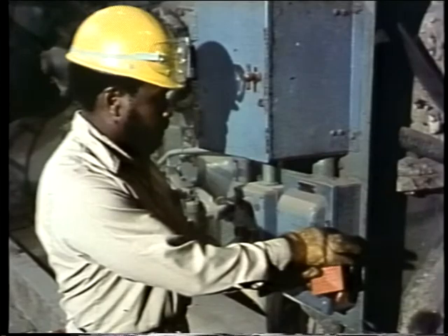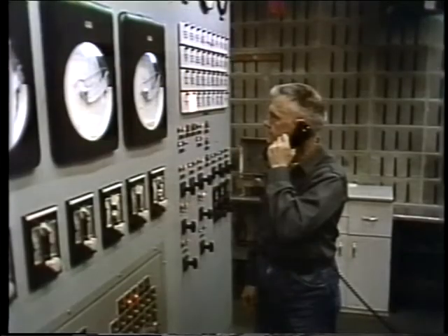Hold tags on the associated systems can then be removed, and operating personnel can run the soot blower through a final test in place. But remember, final testing must wait until the boiler is fired so the soot blower can be observed under its normal operating conditions. Then any final adjustments can be made and the soot blower is ready for some good, reliable service.